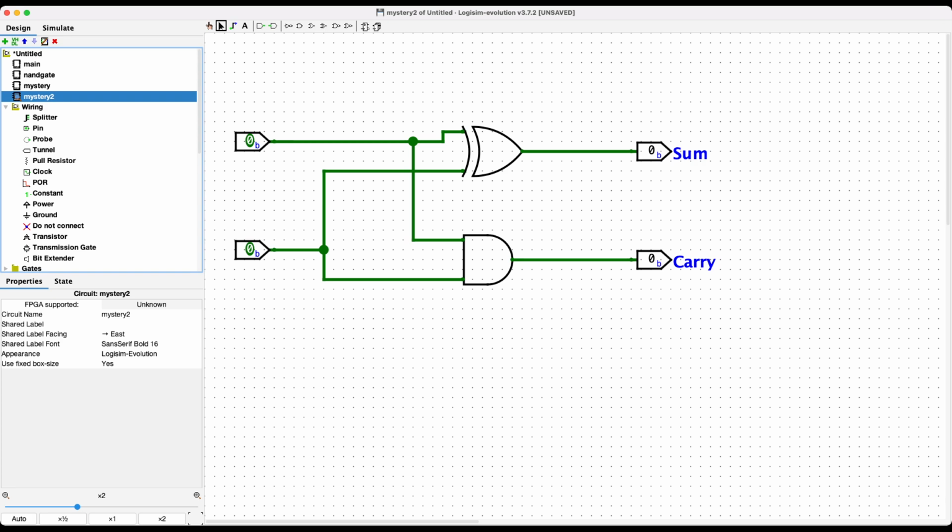But now in this position, what do I have to do? I have to do the same thing, but I have to do more than that. Not only do I need to add the 1 and the 0 like usual, but what else do I have to worry about? The carry that came in. So now this version of the addition circuit needs to have 3 inputs: the 2 input bits and the carry from the previous stage. So the circuit that we've got on the screen right now ain't gonna do it.